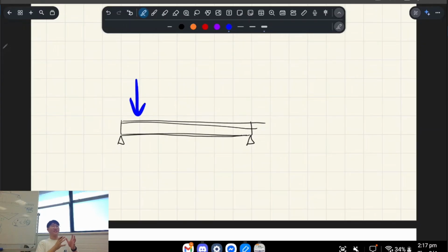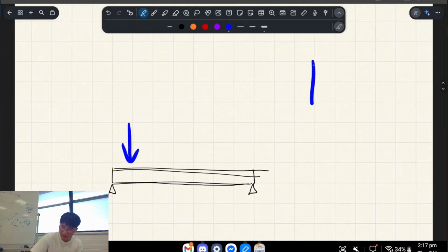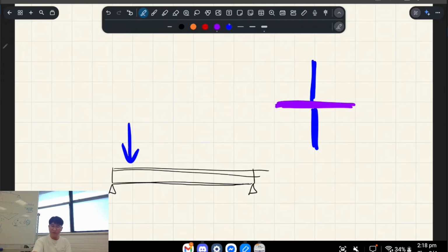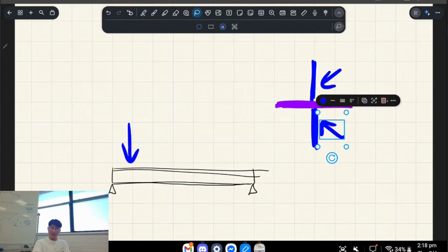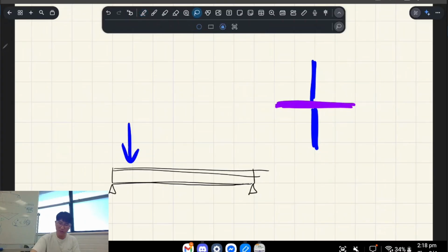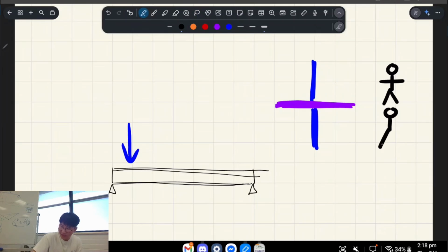And this is the first time I've ever run into this situation because a lot of the time you have a column, say above and below a floor, okay? So that's a floor in purple, and then above you have a column, and below you have a column. So what happens is this is a direct transfer of load. If you imagine it like the stacked toddlers example that I was talking about before, there's no offset of that load.